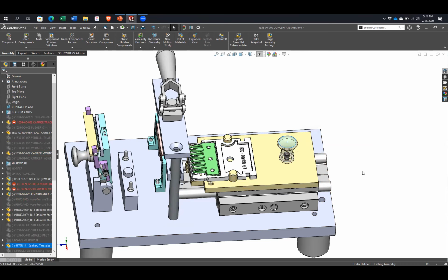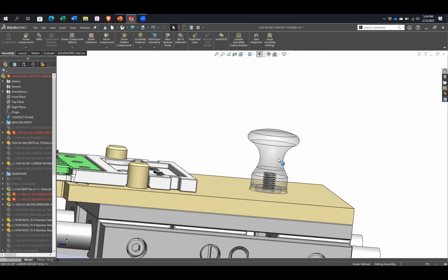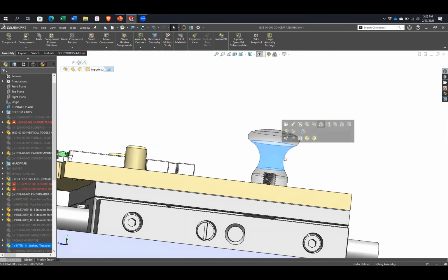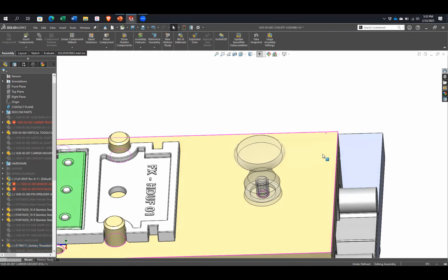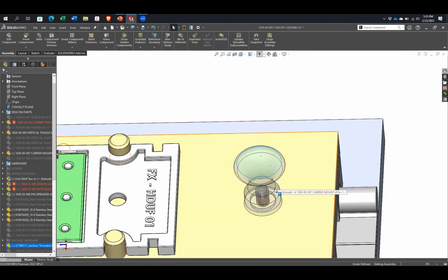It's one of those things that I know people have used SolidWorks for many years and just didn't know existed. Obviously, I think a lot of us play the hover-in-space-at-a-right-angle game, and then you can get it because it's not behind anything. That works fine sometimes, but sometimes you just can't get the right angle. So just hit Shift and now you can select the face.